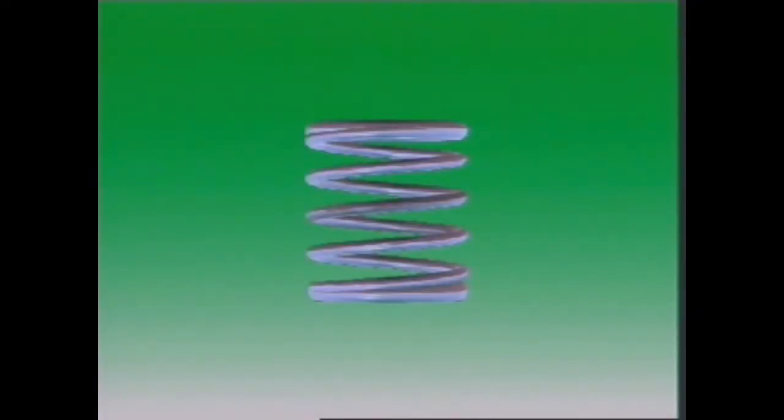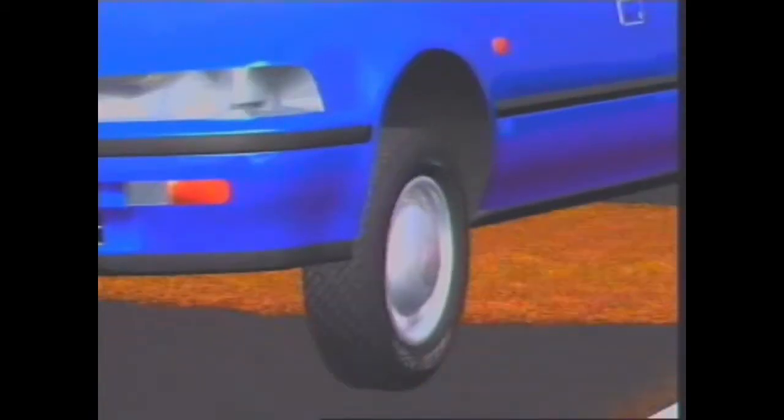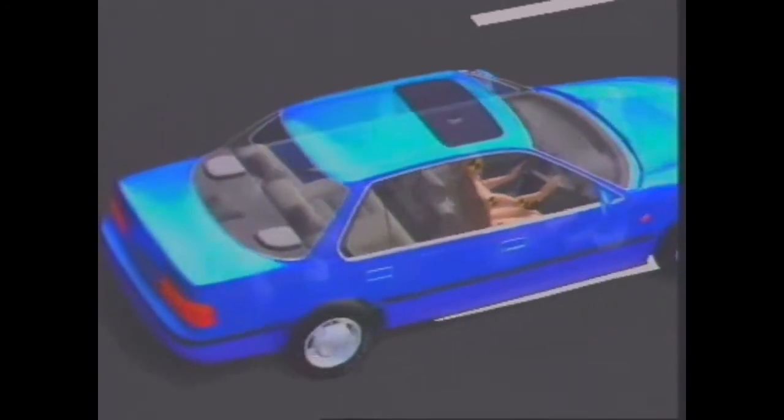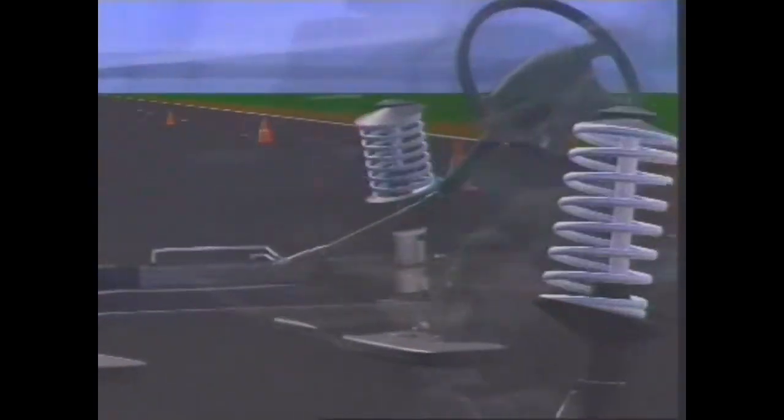When a vehicle strikes an uneven surface, the springs are deformed from their original shape. They return to their original position, but tend to overshoot and set up oscillations. This makes the vehicle bounce up and down, which makes the ride uncomfortable. It can produce forces that make the tyres bounce, and a bouncing tyre won't grip the road surface well. Shock absorbers have a marked effect on how well tyres follow a road surface. They damp the natural bounce over the road and reduce spring oscillations.